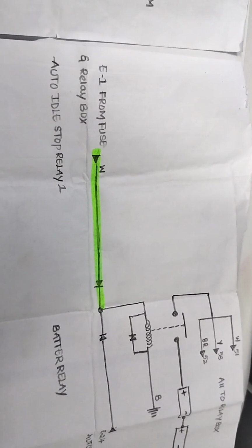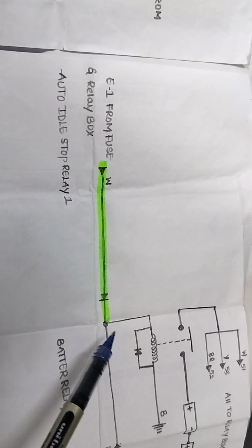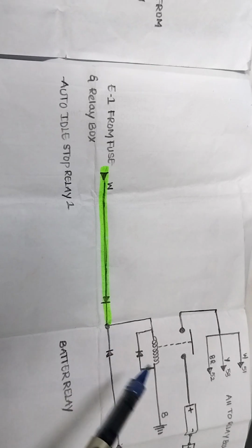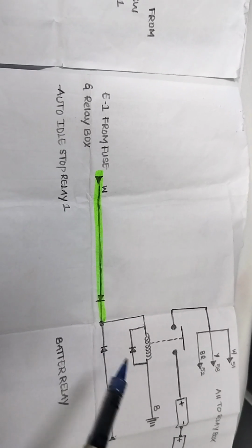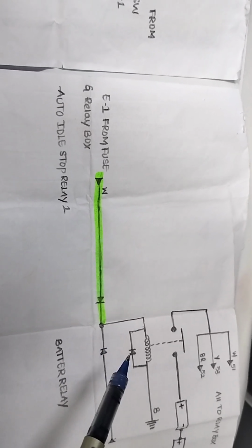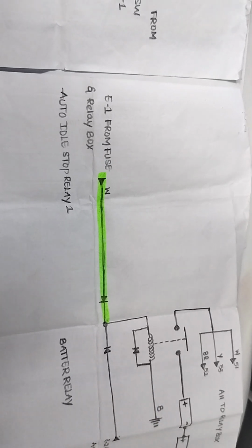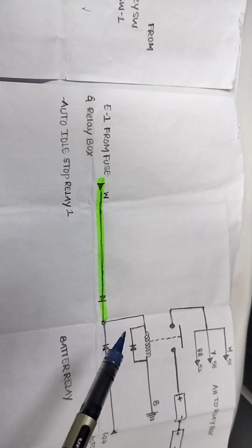Now we are going to start as per the diagram. One thing we need to know: this relay needs supply. To turn on this relay we need supply. From where is this supply going to come? You need to start tracing the diagram. So this is the basic. What is the problem? From where is the source coming to the relay? The relay has an external ground, so what do we get to the relay? Definitely power.